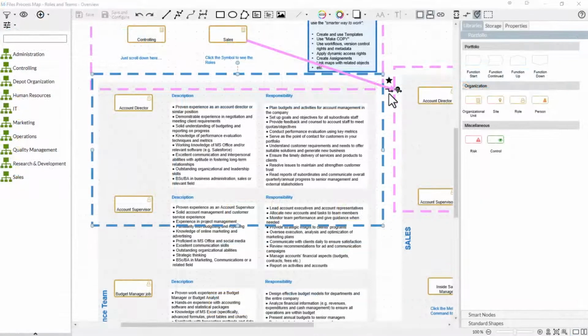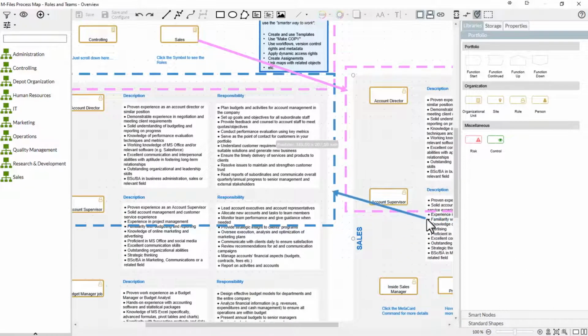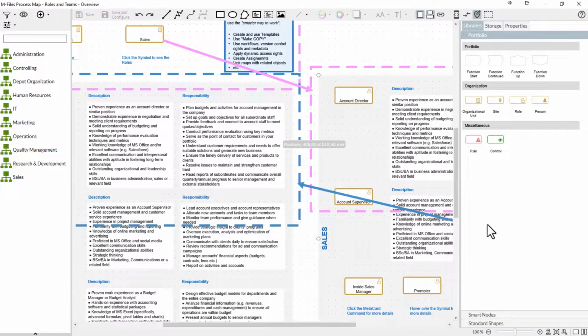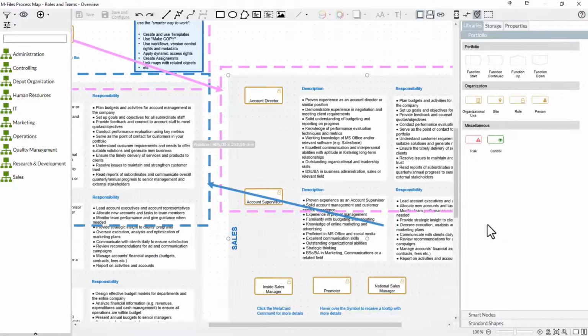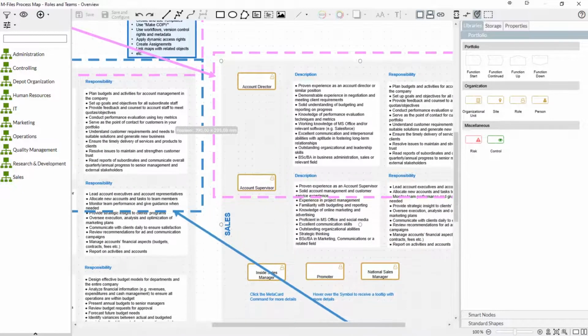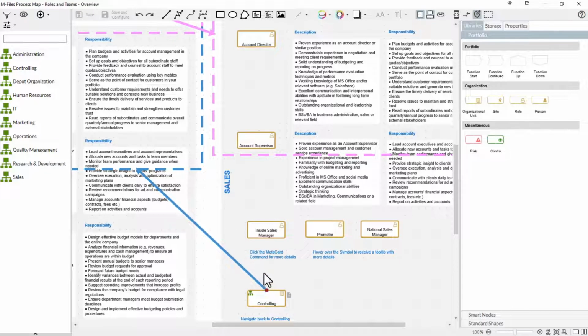Below the star symbol, you will find black icons that allow you to place an anchor for this viewport, either on another element or with a small gray location icon next to an element. Hold down the left mouse button and drag the anchor to snap with the red port of the element you want to link it to. Note that if you drag the anchor into an empty area on your canvas, you will not be able to navigate to it later.